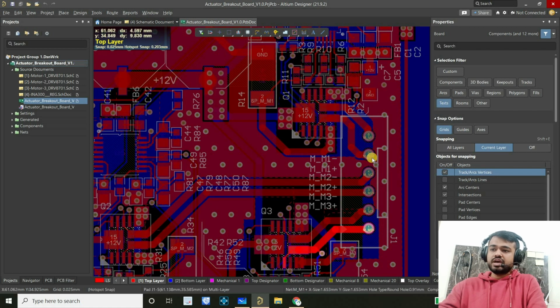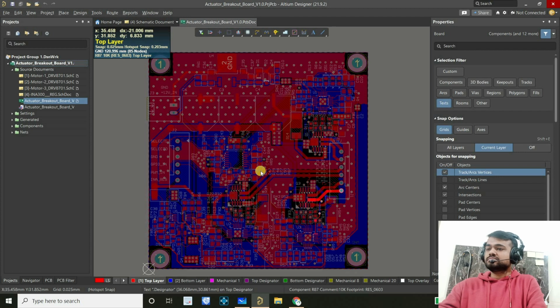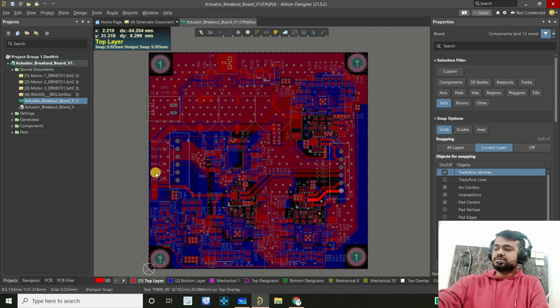Okay, so here we have to connect motors one by one, and I want to tell you the current as well. Each motor can consume 3.5 amps of current. So accordingly, I have routed these traces. And the same thing we'll mention in our power budget. Plus we'll simulate and feed all this information into the PDN tool. So let's start with the power budget first.